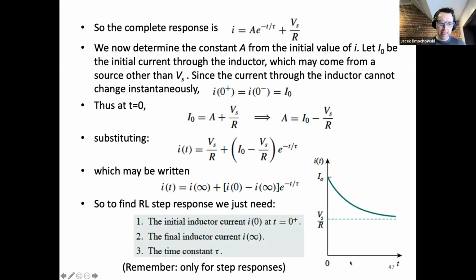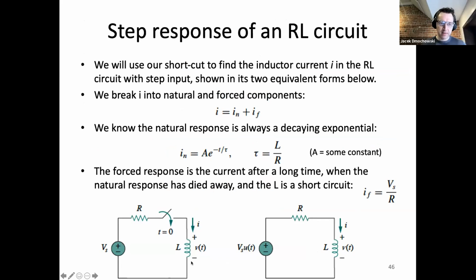So in this picture, when this battery is first connected, there's no current flowing, and the inductor senses all of this voltage. And as time goes by, the inductor has less and less of a voltage until it finally becomes a short circuit where it has 0 voltage, right?